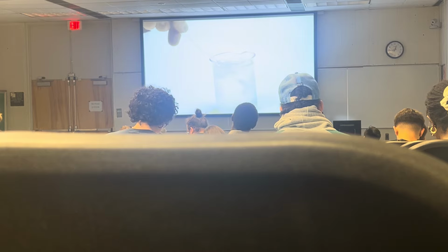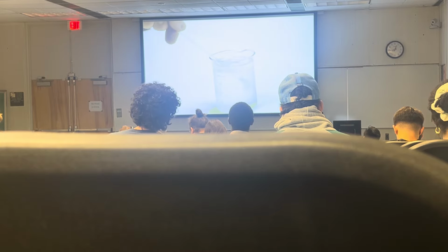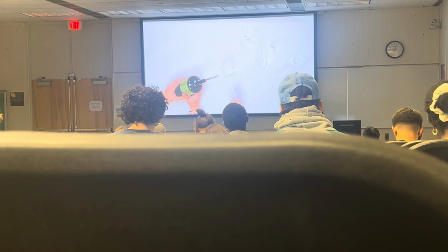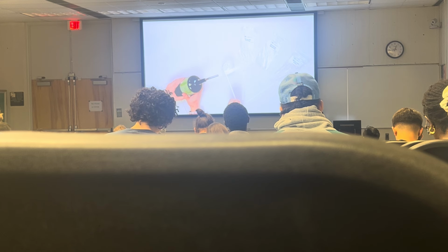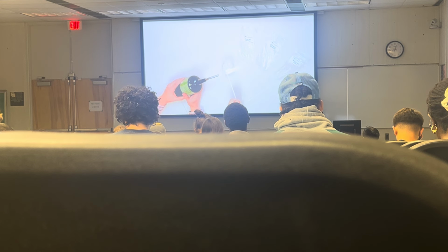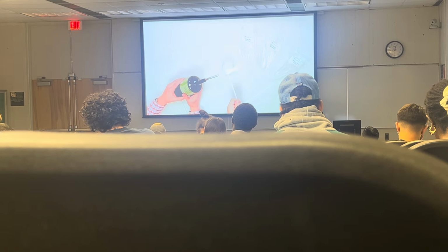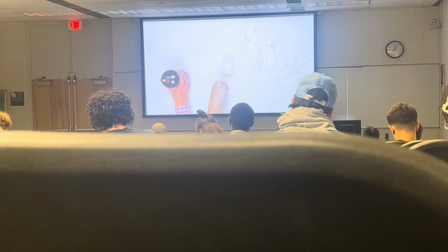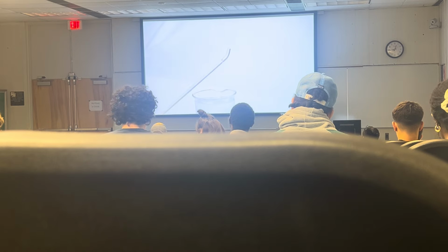Thermal shock will occur and pieces of glass will break off onto the bottom of the beaker. There will be many fractures throughout the portion that was heated. Heat one end of the borosilicate glass rod in the flame, keeping about 1 inch of the rod consistently in the flame. Sagging or slumping should be harder to achieve, but the end should fire polish, become smooth or polished. Some thermal shock will occur, but there should be fewer overall cracks than with the soda lime glass. There should be 1 or 2 cracks at the interface between where the glass rod was in the flame and where it was not.